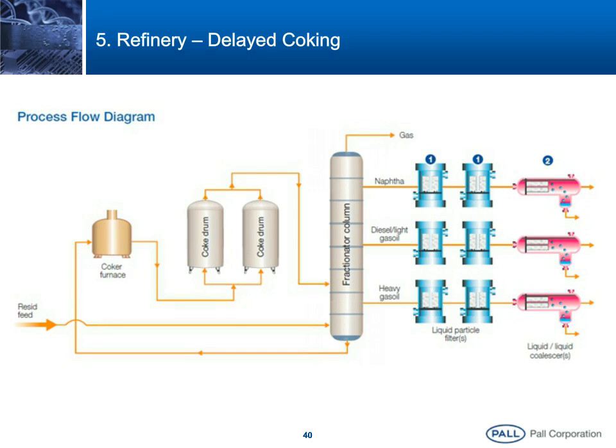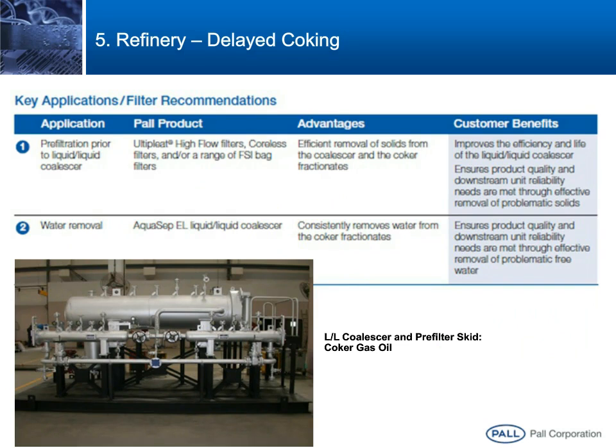So that large volume of steam injection eventually ends up as free water in the various streams coming off of the fractionator. So what we're looking at here is a requirement for high quality products that could be going to final product blending, that could be going to other unit operations, hydrotreating being a pretty typical one on many of the streams coming off of a delayed coker. And we're seeing the installation of particulate filtration and liquid-liquid separation to ensure high quality on these streams.